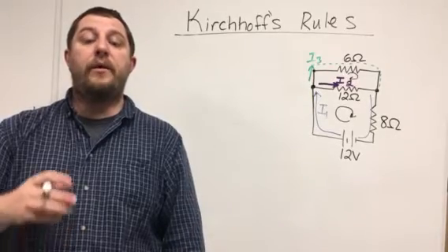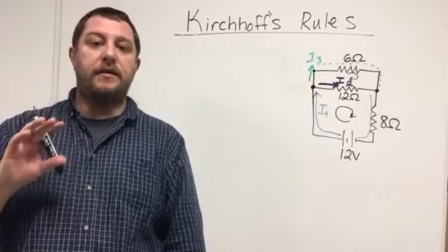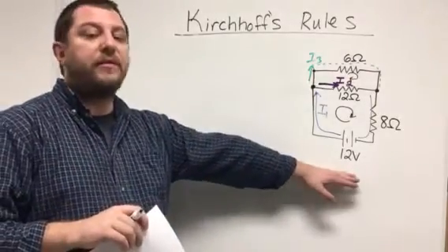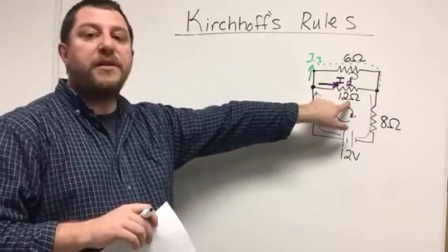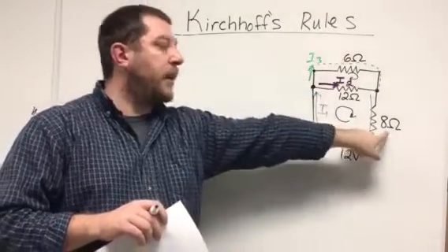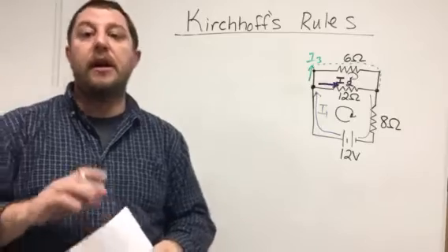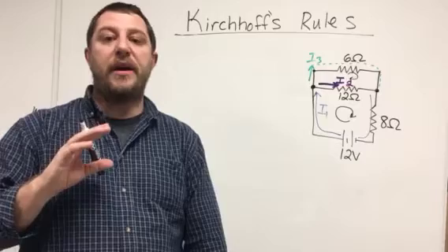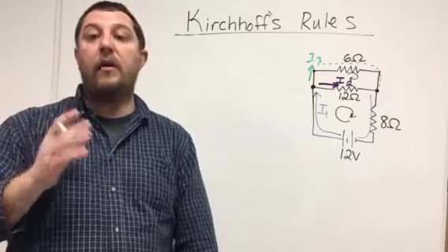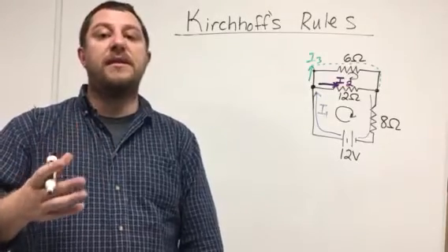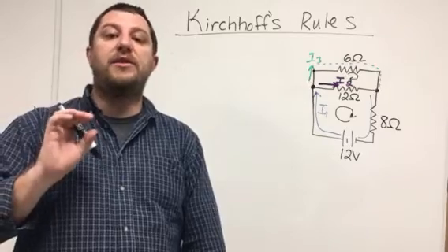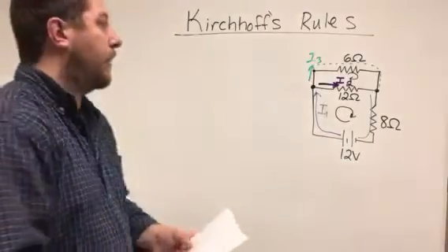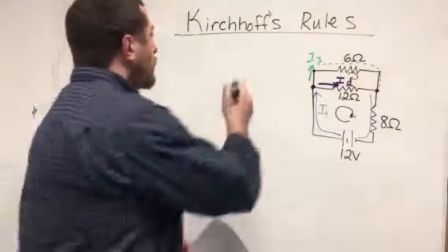We now want to go about actually solving this problem for these currents in this circuit. So let's suppose we have a 12-volt battery, a 12-ohm resistor, a 6-ohm resistor, and an 8-ohm resistor in this configuration. Now, as we said before, we can actually find the currents using series and parallel circuit rules, and we'll do that at the end and show that this is consistent with those, but let's just see how Kirchhoff can be applied to get us started with these types of problems.